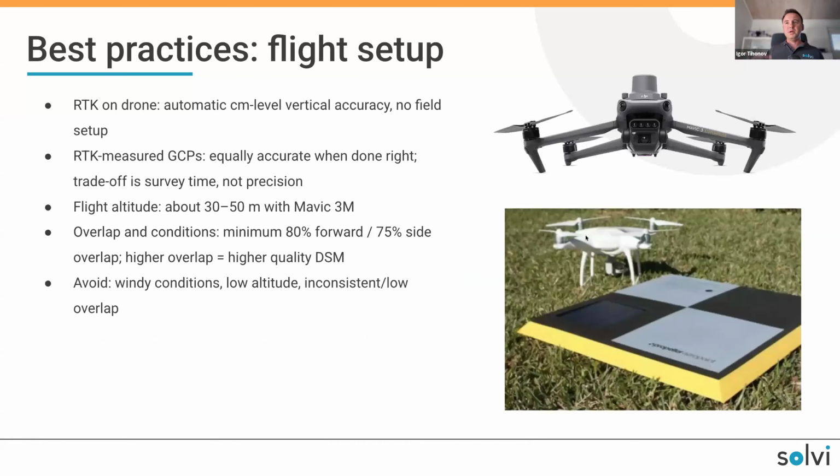So a few words about the best practices for the data collection, because as you by this point probably understand, the single most important factor that affects the accuracy of height measurements is the quality of these elevation maps. If they don't turn out well and don't represent what it looks like in the field, then all the measurements, whichever method you use for height measurements, will not help. And the quality of the elevation map mainly depends on a few factors.